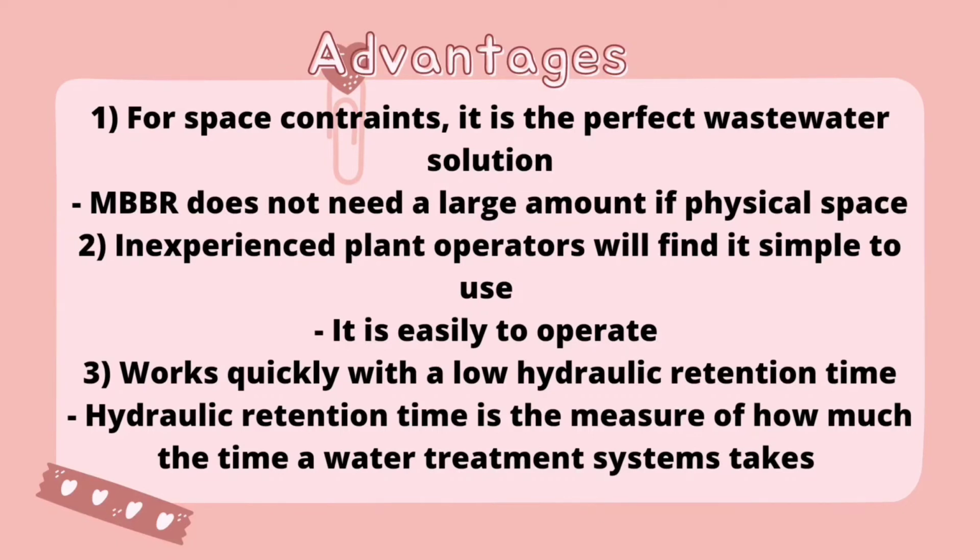The last advantage is that it works quickly with a low hydraulic retention time. Hydraulic retention time is the measure of how much time a water treatment system takes to effectively treat the effluent. For some systems, this can be a long time, which means the process moves slowly. The slower the process, the less wastewater can be treated in a given amount of time.